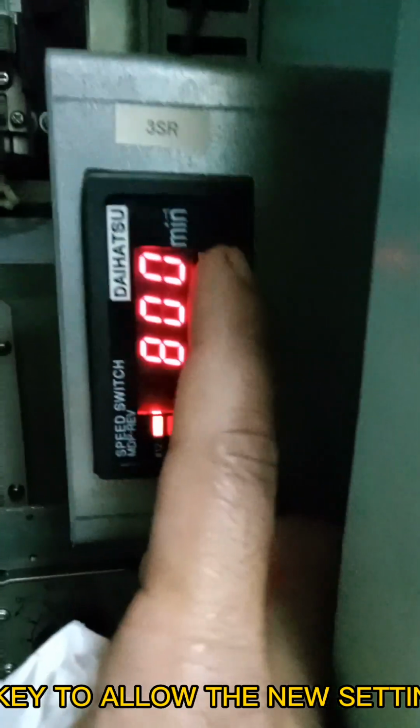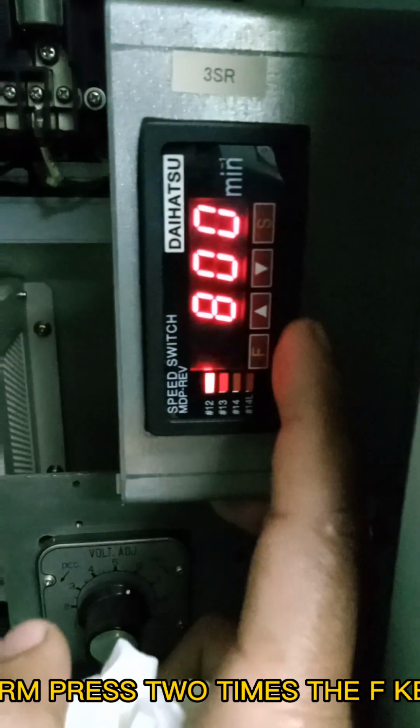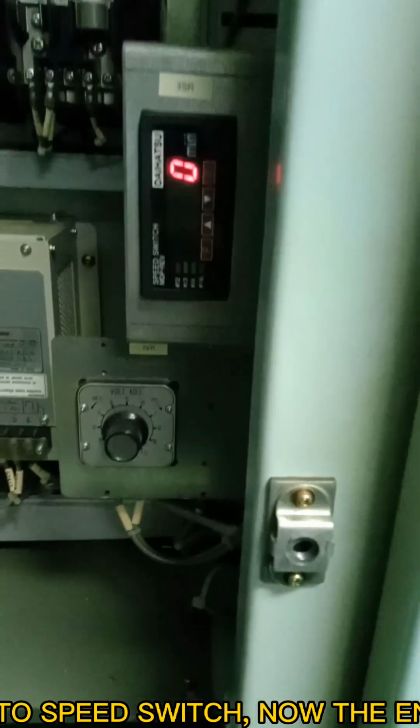Long press the S key again to allow the new setting to register in the system. When the flickering stops, this means it is registered already. To trigger the trip and alarm, press the F key 2 times. To reset, you need to put the throttle lever on the engine side at stop position, then go back to the speed switch.